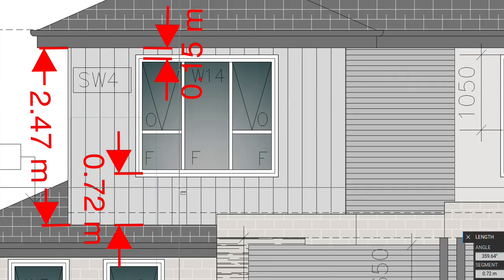That's 870 into 9, sorry, my bad, that will be 7.83 linear meters. Accurate. And if you divide it by the length per panel, which is 2.9, you can take 3 or 4 panels maximum, 4 panels. Now there is 10 plus 4.